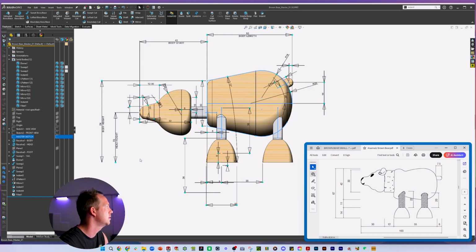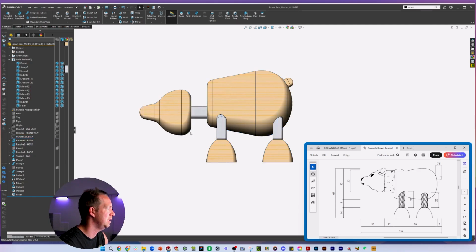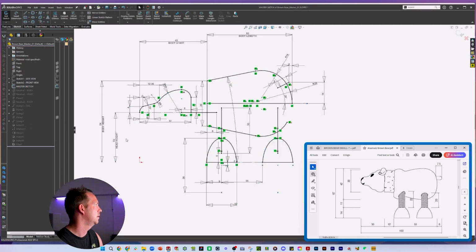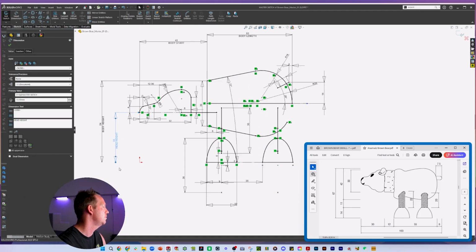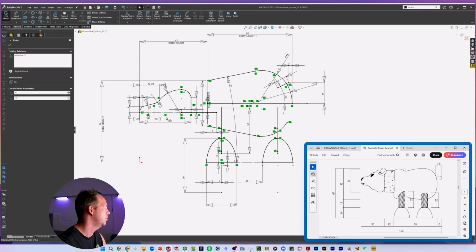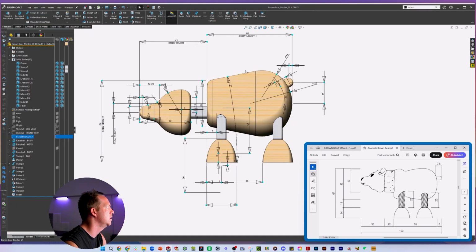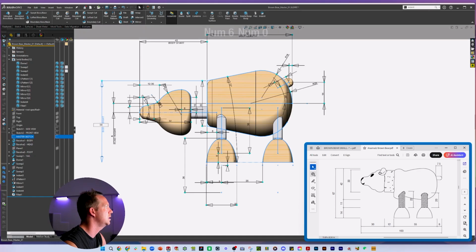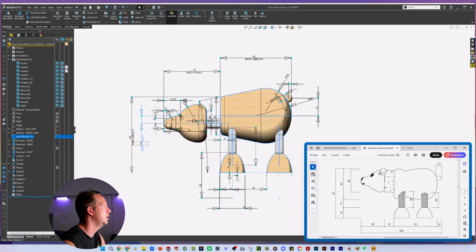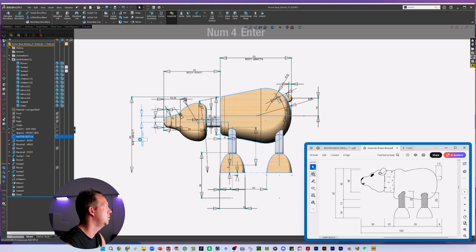So the height, we want to change the body height, or do we want to make the head height referencing the body height? It kind of feels like the head's a little bit low, doesn't it? So here, again, where the head height is currently referencing the origin, let's get it to reference the center point of the head. Now, if the body moves up, the head will move up like this. Body height, change to 60, everything moves up. I think it should be a little bit higher, so I'm going to reduce it to 5. A little bit higher, 4.